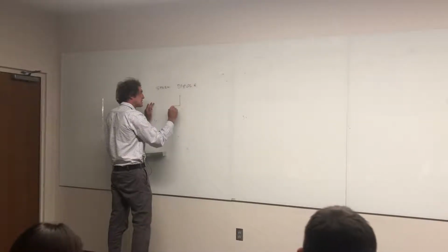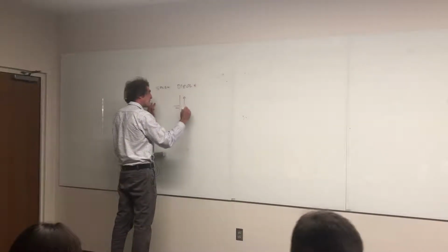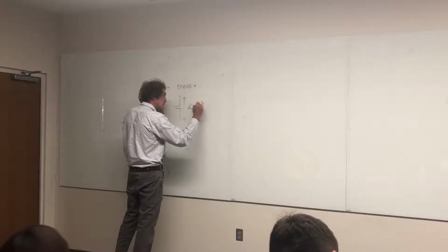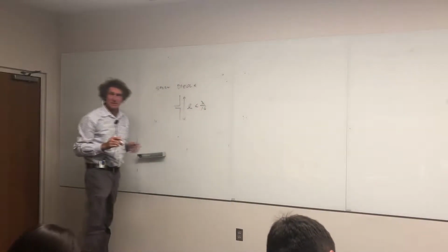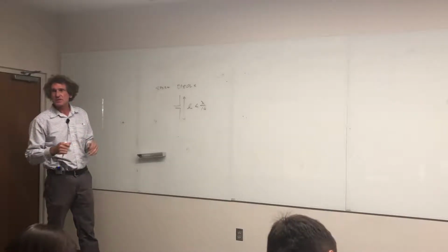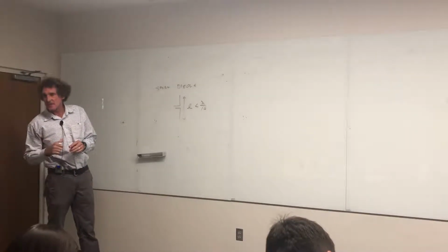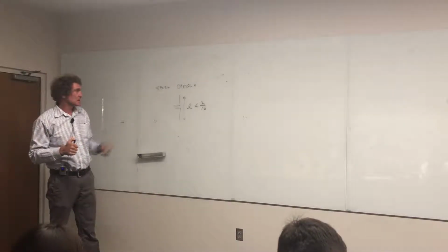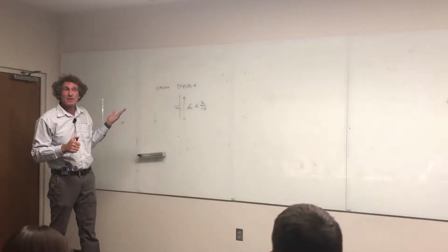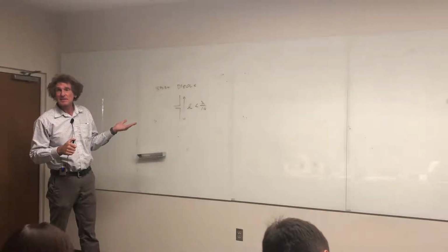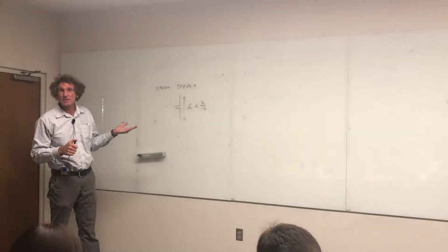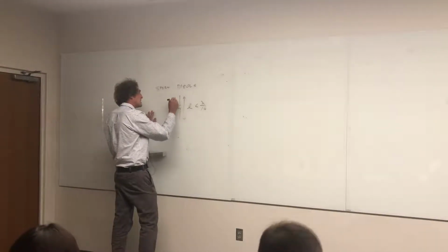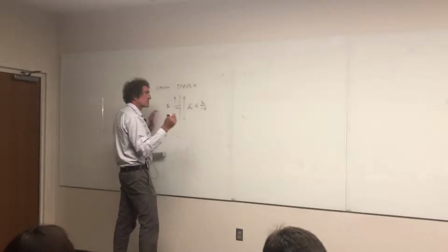that assumes the length of the antenna, L, is going to be less than lambda over 10. The book will say much less than lambda, but really it's just less than lambda over 10, a tenth of a wavelength or less. All right, so that's a short dipole. From that, if this has a current I naught here, these are the characteristics.